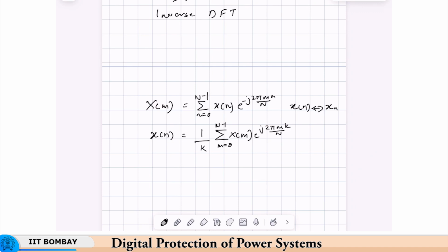We mentioned c last time. Okay. So, now if this is a proper transformation going from the time domain, discrete samples in the time domain to the frequency domain, then it is possible to have an inverse transformation restricted to m frequencies in the discrete domain, such that you can get the n samples back, and that is this transformation which we call the inverse DFT or the inverse discrete Fourier transform.